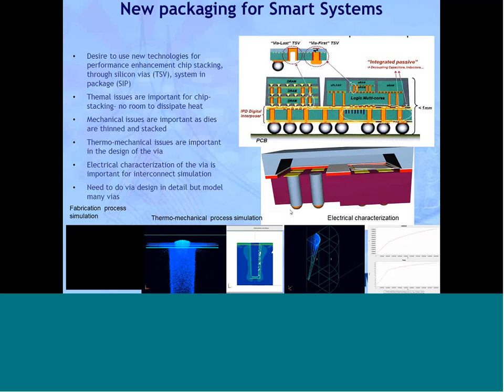I hope I've given you a little bit of an overview of how the MEMS Pro tool suite can go from simulating things like fabrication effects through design rule checking and verifying the MEMS structures, and also talked a little bit about how we can simulate electronics and MEMS together so that you can take an overall system approach to design.